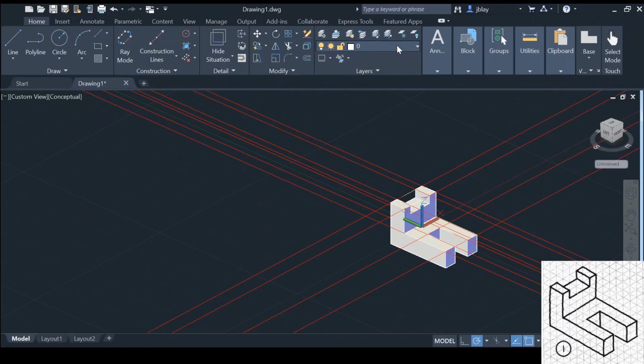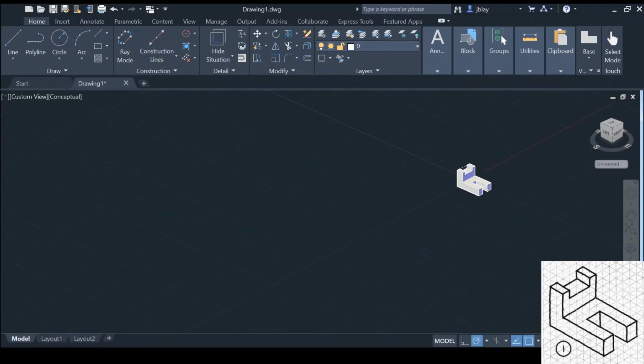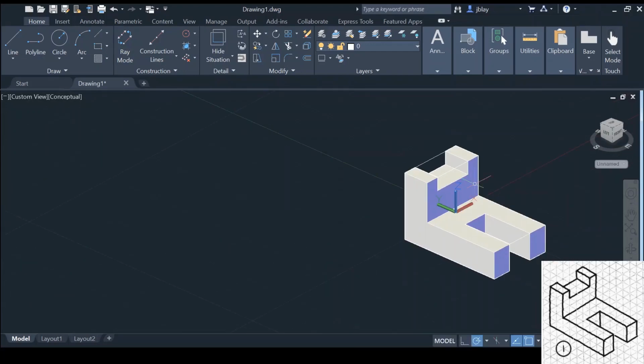We can go ahead and turn off our construction lines. You'll notice you'll have some lines left over, which is what tends to happen with press pull. If they're kind of in the way, you can delete them, if they make the shape look kind of ugly. But here it is, finished product. We can go into X-ray so we can see our intrusions really well. But that's it.